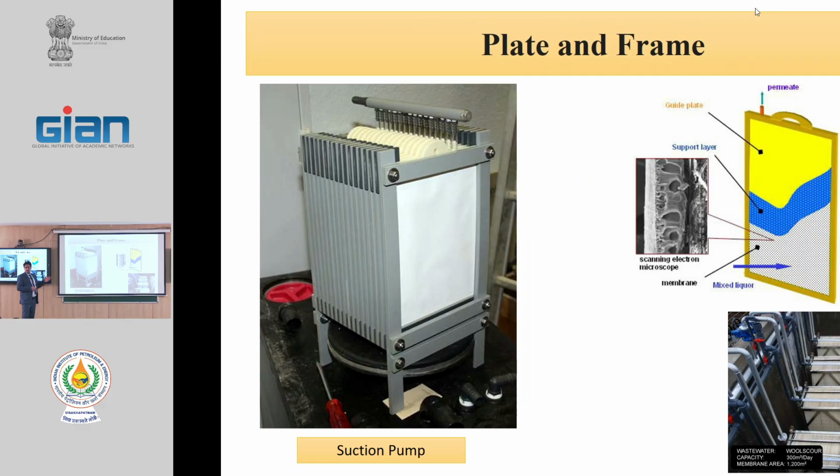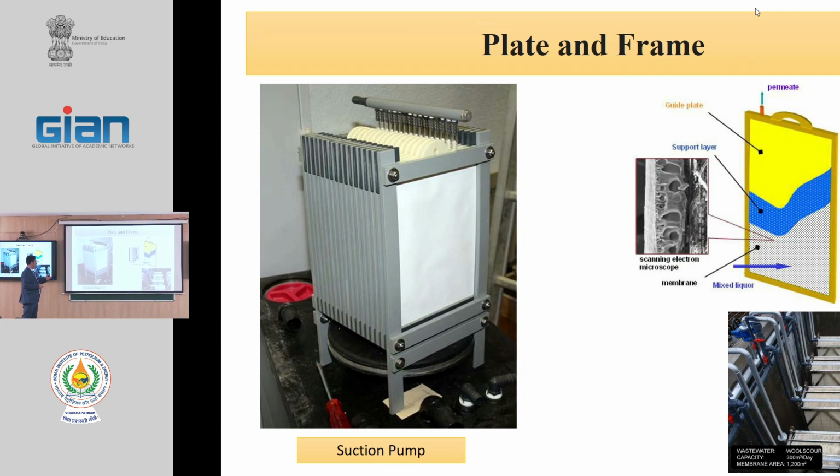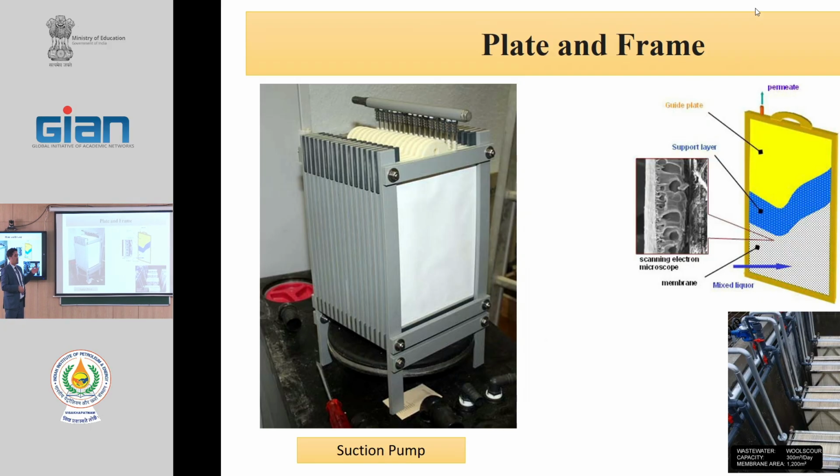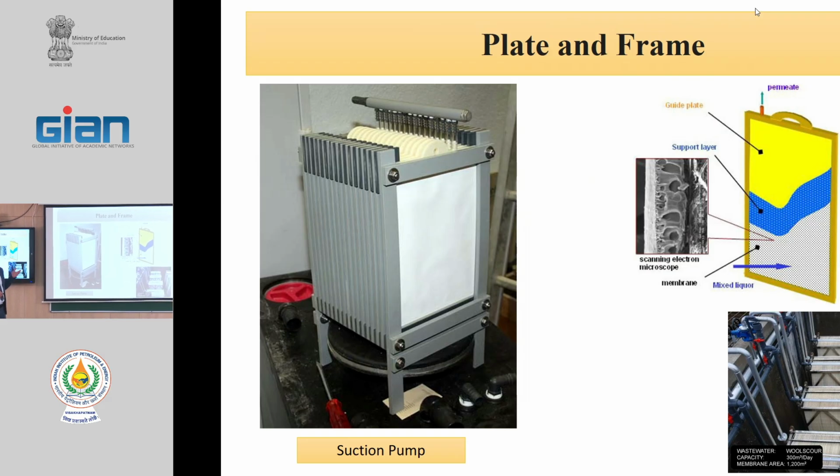They are very good modules from the fouling view because we can purge air or oxygen on the surface of these modules, and cleaning of these modules is very easy. With a sponge, we can clean these membranes for removal of the microorganisms and other dirt.